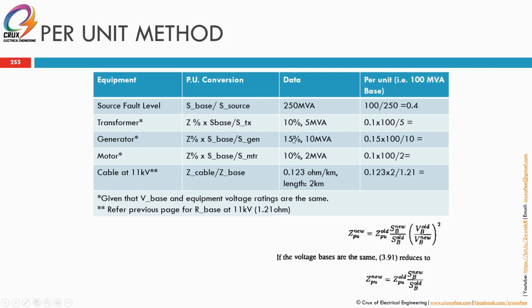If it's given to you in kilowatt and power factor, you need to convert them to MVA first. For motor, you have to convert them to MVA first, because normally they don't provide you in terms of MVA. So you have to know the kilowatt and the power factor. You convert that kilowatt divided by the power factor and you get the MVA, then you calculate the motor lah.